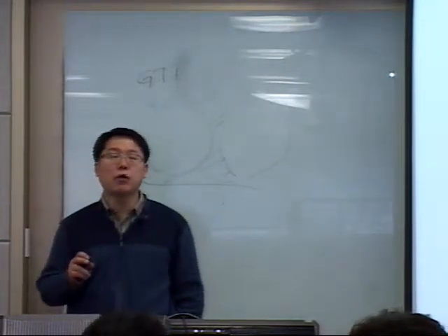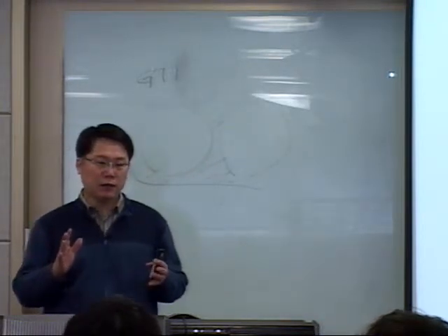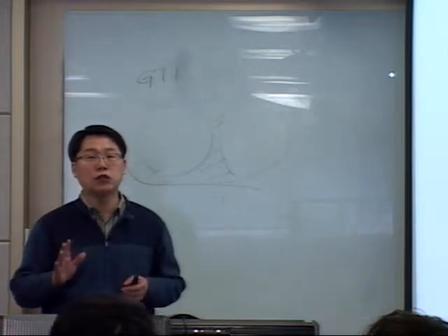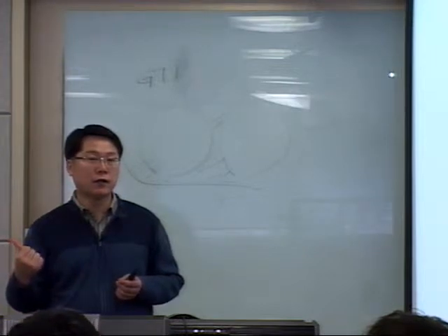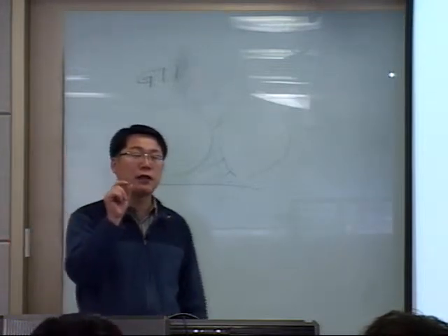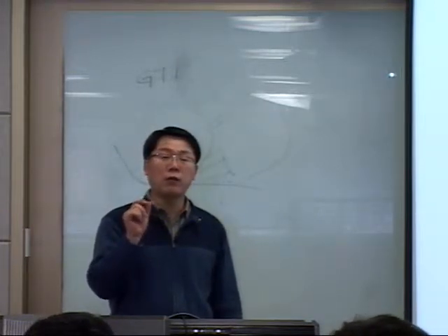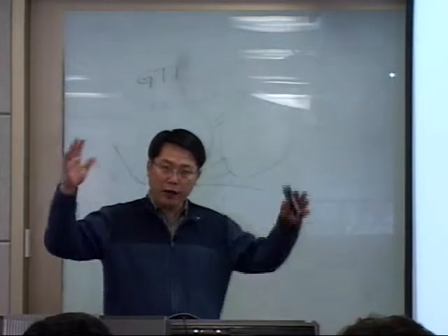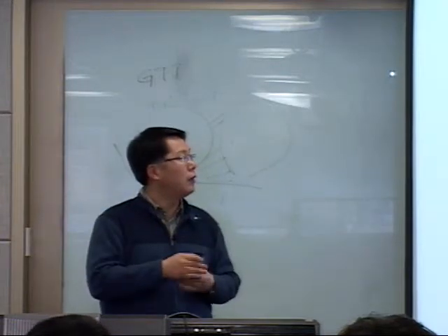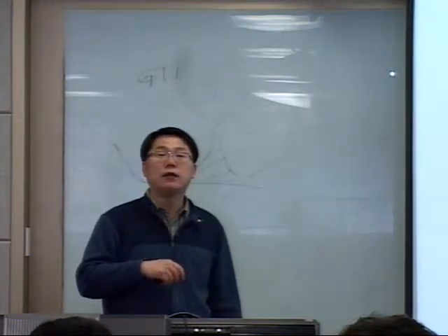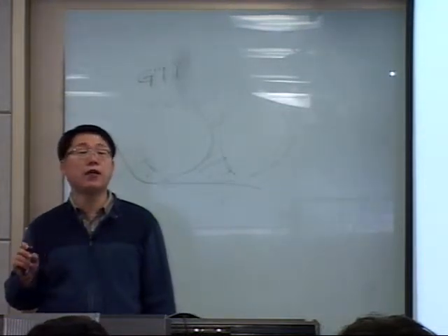These two are playing the role of containment, and their role is to prevent leak from inside to outside. So the thickness is a little thin, 1 millimeter. Okay, we have two 1 millimeter layers to contain the LNG inside it, and the other layers' role is insulation against heat ingress.